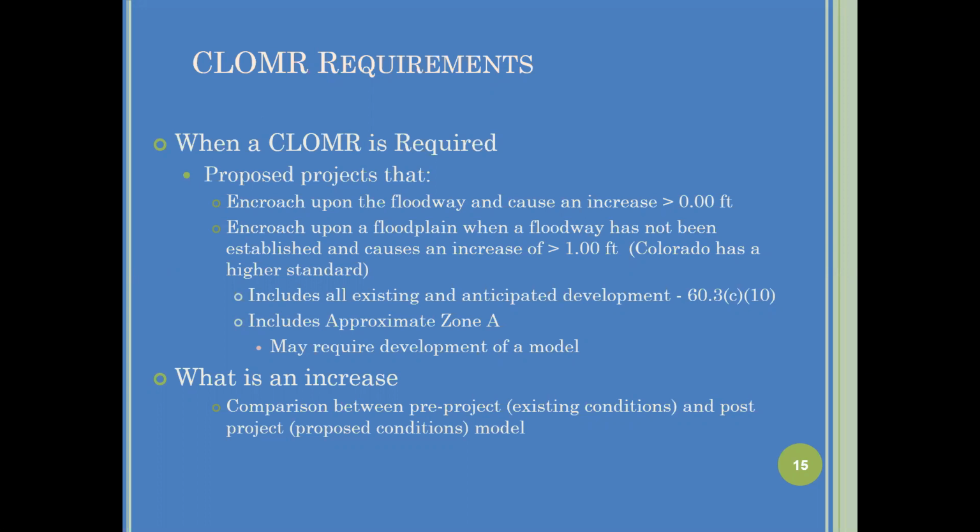If the local community's floodplain permitting maybe lasts a year and the project is supposed to be built within that time, and they pre-approve floodplain permitting and then the as-built data changes that, can the developer use that as-built data to submit that LOMAR, or does it have to be the design that's approved and does not cause increases in flooding?